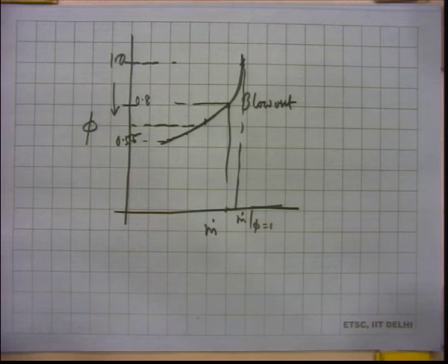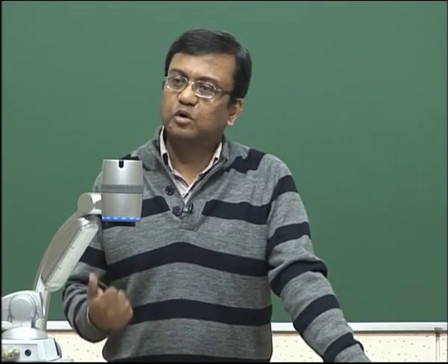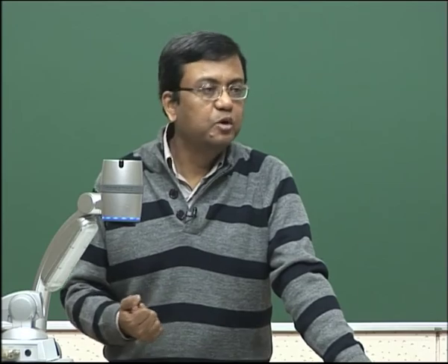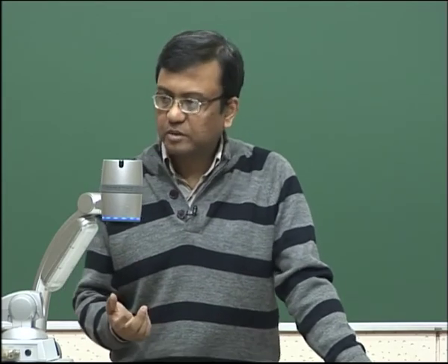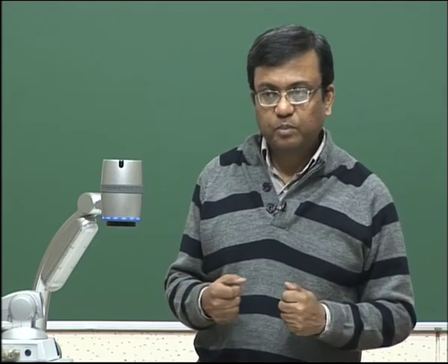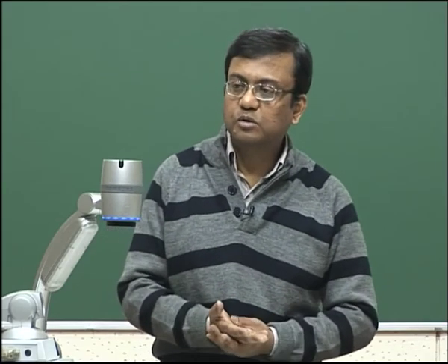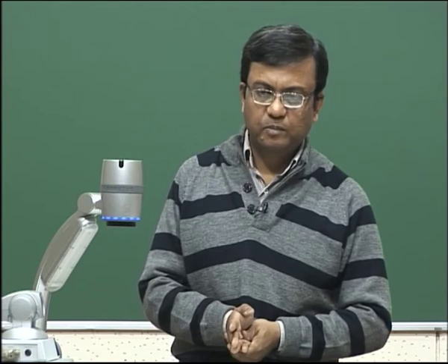Now, very quickly, we do not have much time left. Does this plot tell you that lean mixtures have a tendency to get quickly blown out, or in other words, a stoichiometric mixture will be able to tolerate higher values of m dot, right. It will get blown out only for large values of m dot. Lean mixture gets blown out for much smaller value of m dot.